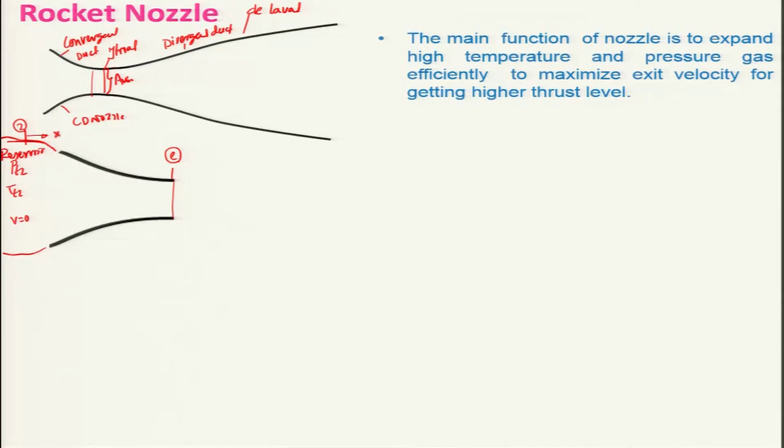And let us see what happens when you consider a pressure here, what we can call back pressure at the exit of the nozzle, which can be changed in a laboratory by changing the pressure. However, when an aircraft or a rocket engine or any other propulsive device moves with altitude, the ambient pressure will be changing, and that is nothing but your back pressure. That means the nozzle will be subjected to variable back pressures.